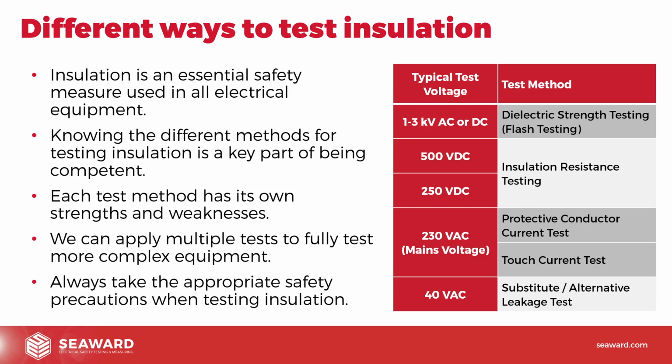So really, dielectric strength testing or flash testing would be an example of a very hard test. It's going to be quite rigorous on the equipment, but it is going to find those faults. It is really going to put that equipment under some stress. But again, you do run the risk of damaging the equipment or potentially damaging yourself while you're doing it.